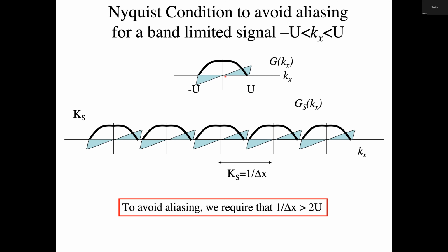There are some very easy examples of band limited functions, right? So if I have a plane wave, a sine wave in the plane, then sampling beyond that sine wave, if I go far enough, it doesn't matter, right? That's the only frequency that's there. If I sample some function that is a composite of sine waves, and then you stop adding sine waves at higher frequencies to make this Fourier composition, then beyond those frequencies, there's nothing there, right? So it's a band limited function.